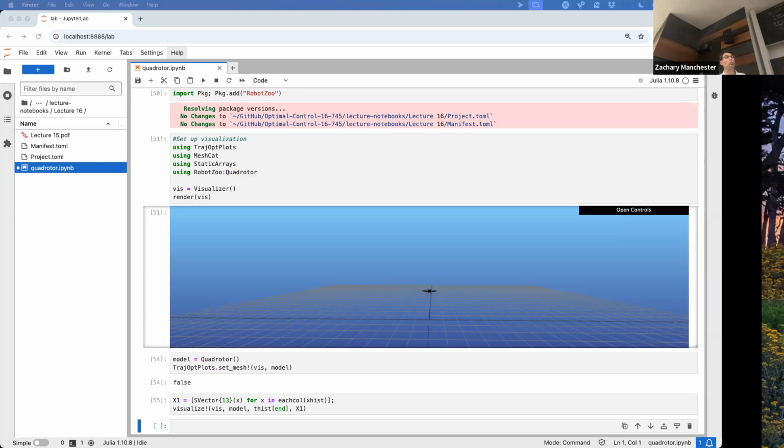And then you run nonlinear trajectory optimization on that nonlinear model, where you take a few Newton iterations. If you can do that fast enough, which often you can, you just do that online and run nonlinear MPC. If you can't do it fast enough, you could do it offline, where you optimize some crazy barrel roll thing. Then you would linearize around that barrel roll trajectory, get a linear time varying model, and then do time varying LQR to track it. And that would work really well too, right?